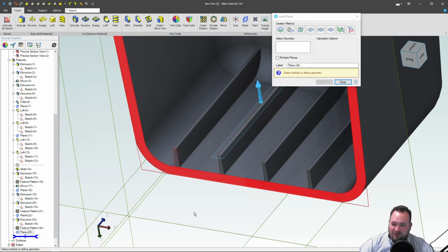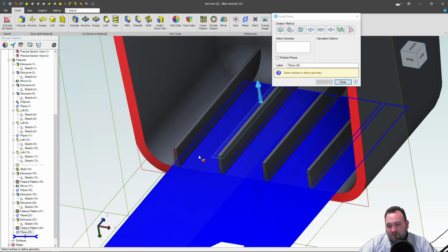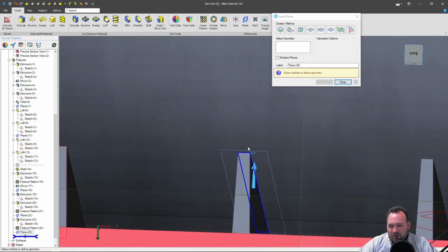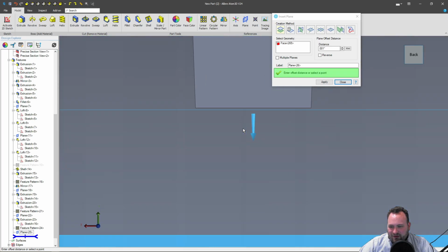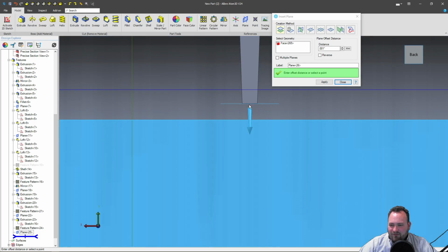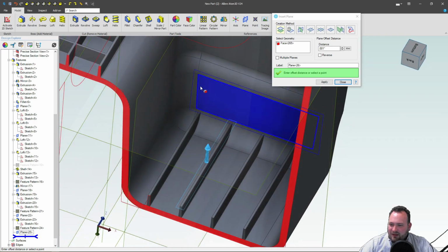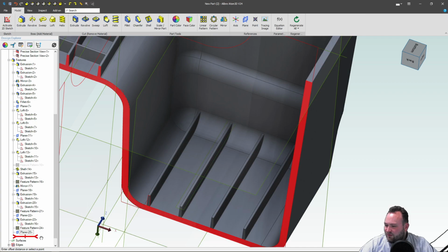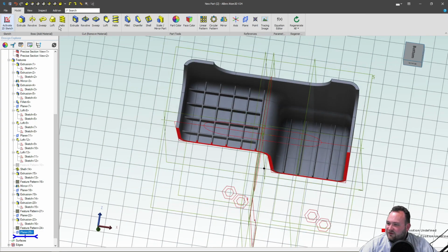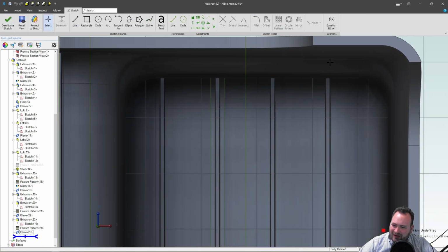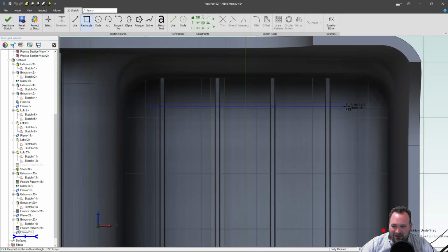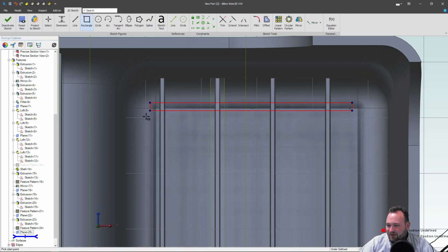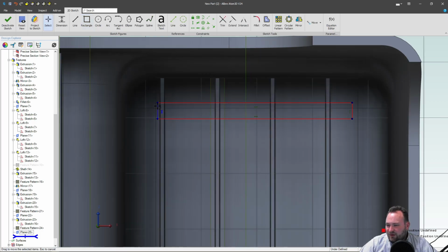So we can just change the rib height slightly like we did last time. Or I'm making a plane here that, as you can tell, just has this tiniest gap above the rib. And we'll close that, right? So I'm going to grab my plane, create a sketch. Here's another way of doing it in case you have some more fancy design intent, like a more intense uneven surface or something. I'm going to draw my rectangle and just go past both ribs.